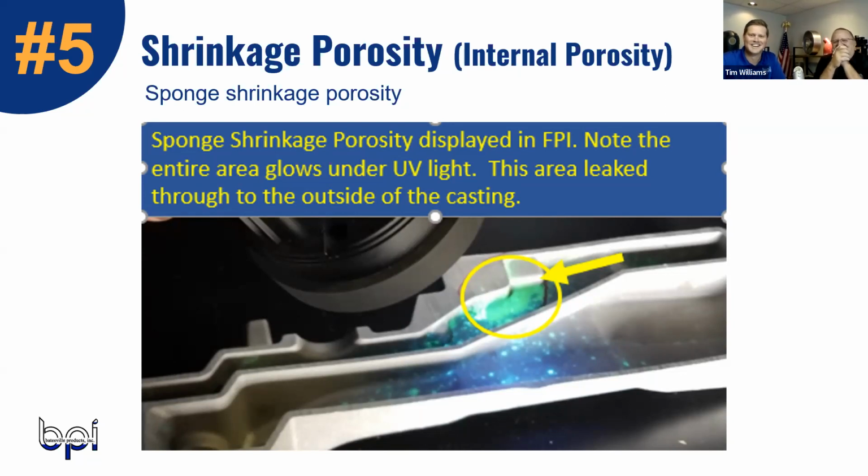Very good answer. It's a great question because again, every product has different processes like sand casting, die casting, permanent mold. We even talked a little bit about the vacuum process, and every process is going to have some different needs. But when you get into products, every product's going to have a different way you need to fill different critical areas. Risers are never the same. They're always built for a particular job.